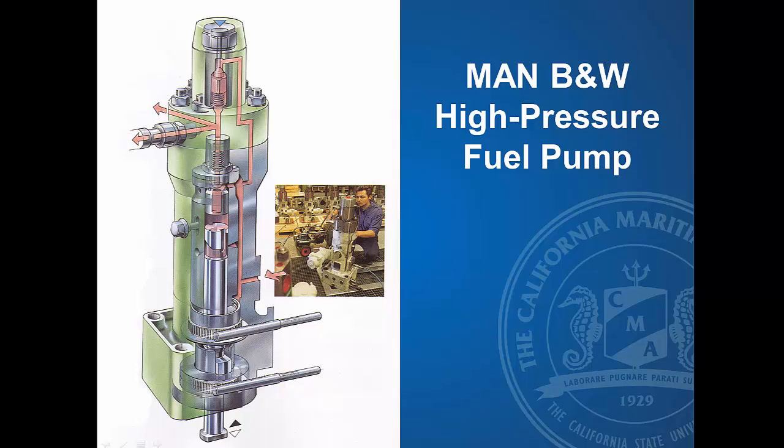And it can raise within that housing. The other thing I want to mention at this time is there's not separate spill and suction ports on that barrel. They basically both act as suction or both act as spill, depending on where in the cycle you are. The incoming fuel is going to be around the entire outside of that barrel.